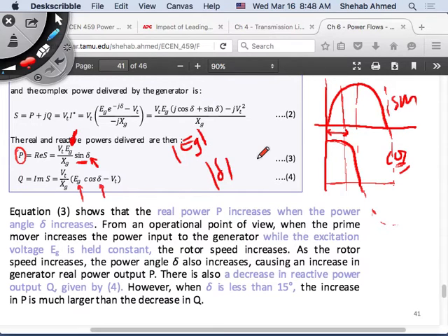And then when we saw the example that we went through today, we saw that all the buses had voltages close to 1, but that one bus that had the largest reactive power, the voltage was like 0.87 or something like that, right? So voltage doesn't change significantly. And we will see why from the phasor diagram.